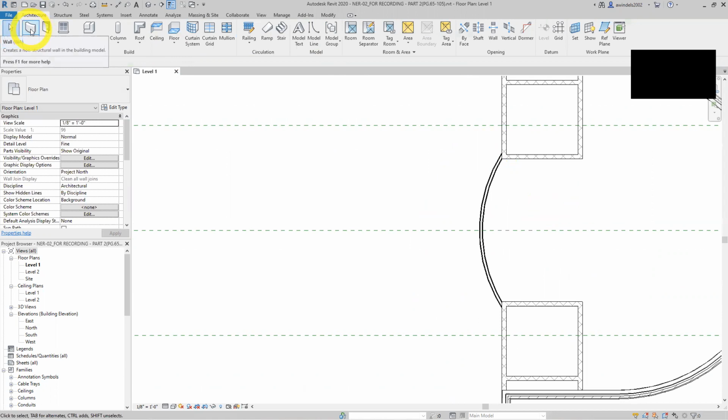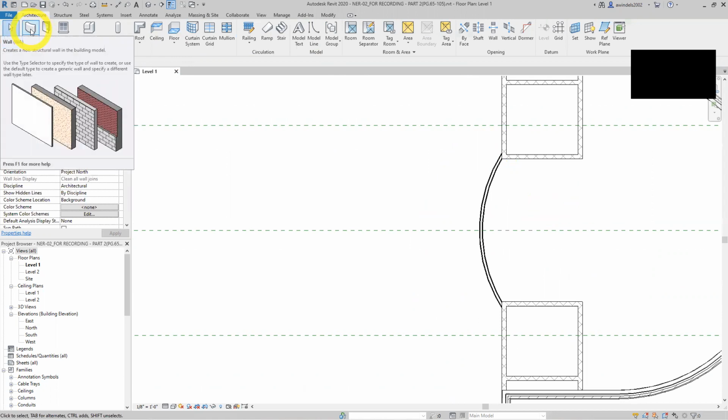We're going to start our next walls, and we're going to mirror it with an offset about our reference point in the very middle. If you look very close on page 71, that's going to be our pick point. I'll zoom in there in a minute. We're going to use that as our basis of mirroring or offset, so we can build the 2 corridor walls in the middle very quickly and easily.